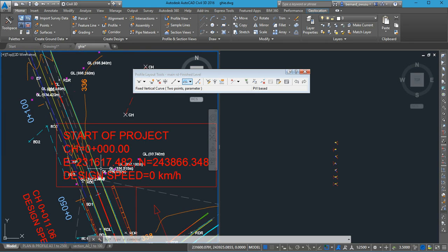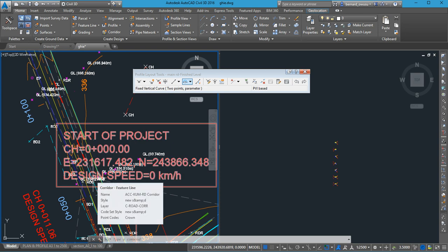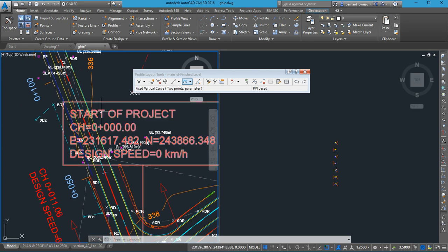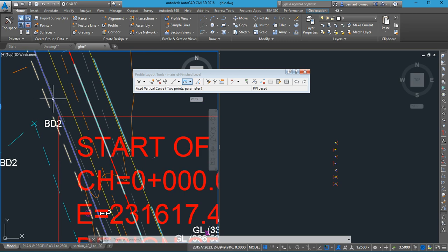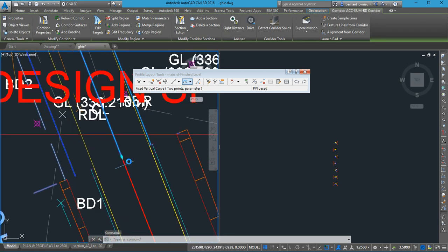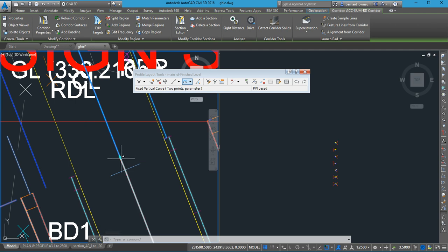So who was successful? Who has a corridor created for him? Successful. Yeah. I started from the... Because I told you to change the start. You do not change, but at least you have it. Even if you have it wrong, you can always select the corridor and change the start point. You see that there's something like a diamond at the beginning. Come and hold it and you can drag it to wherever you want it to start or end.